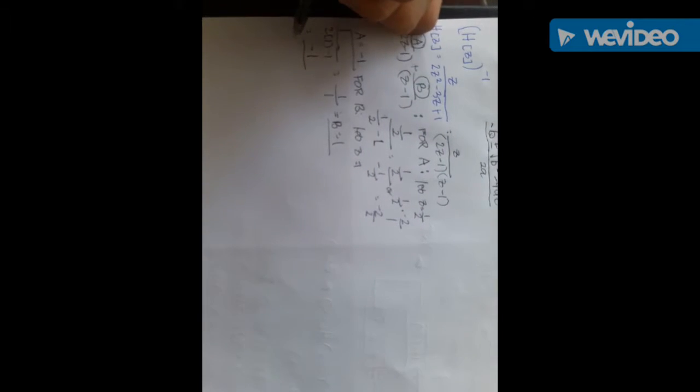And this value we will plug in, or directly substitute, into the partial fraction identity, which has negative 1 for a over 2z minus 1 plus 1 over z minus 1. So as we observe here, we will not be able to get a z transform identity because of this value. So one way to get a proper identity is to find a way for this equation. In this case, we need to divide it directly using the long division method, or we can do another partial fraction, doing the h of z over z.